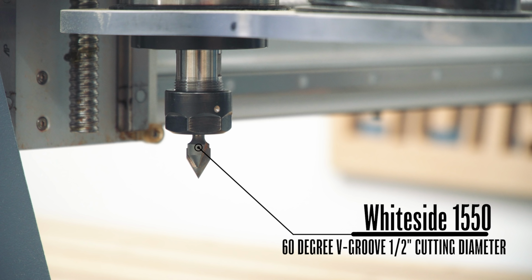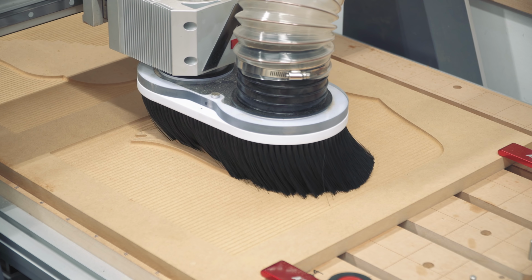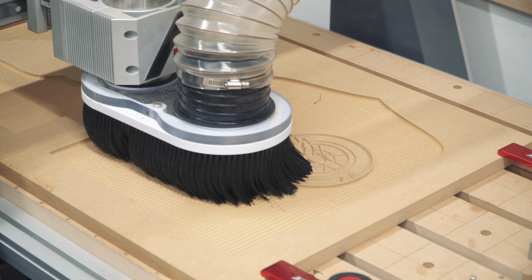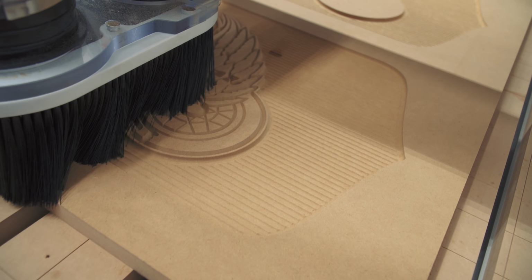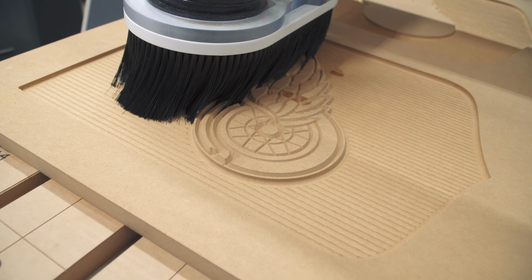The second bit to be used is this 60-degree V-bit for the logo. And the V-carve toolpaths are just really interesting to me because you always get such precise shapes out of them. The software calculates when to lift the bit to create a nice, sharp, crisp corner, so you're not limited to the radius of the bit for interior corners. Everything's just always crisp and sharp, especially in MDF.